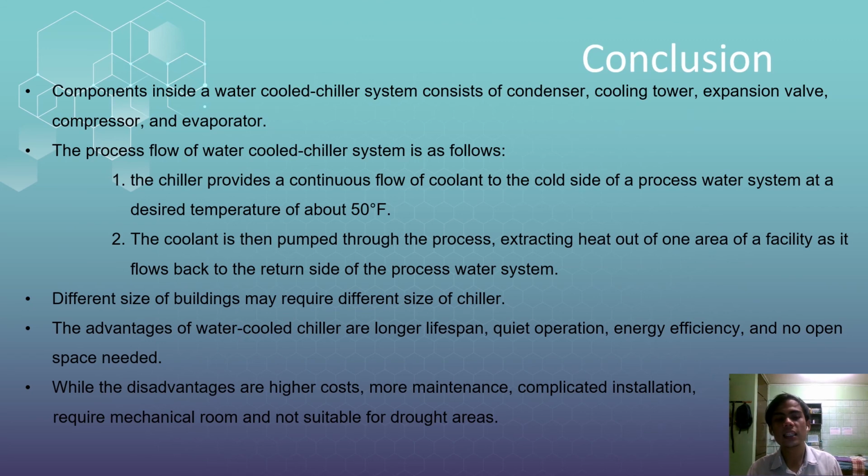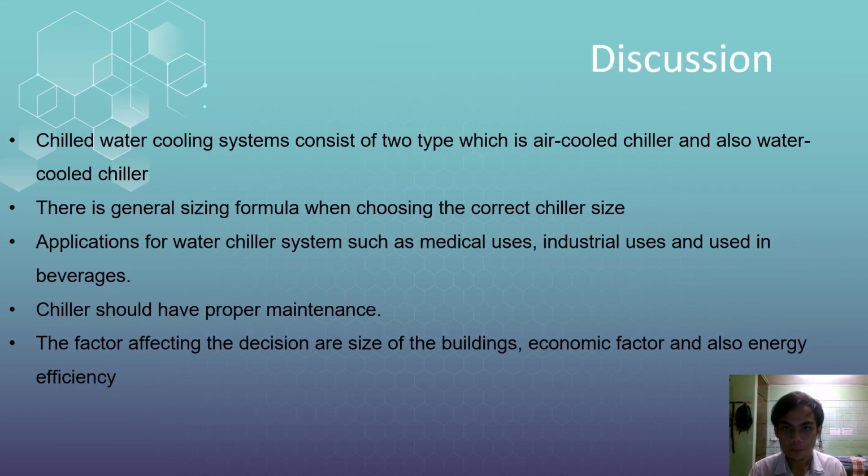Next are the advantages of water cooled chiller: longest lifespan, quiet operation, energy efficiency, and no open space needed, while the disadvantages are higher cost, more maintenance, complicated installation, and not suitable for drought areas such as countries like Egypt and Saudi Arabia.